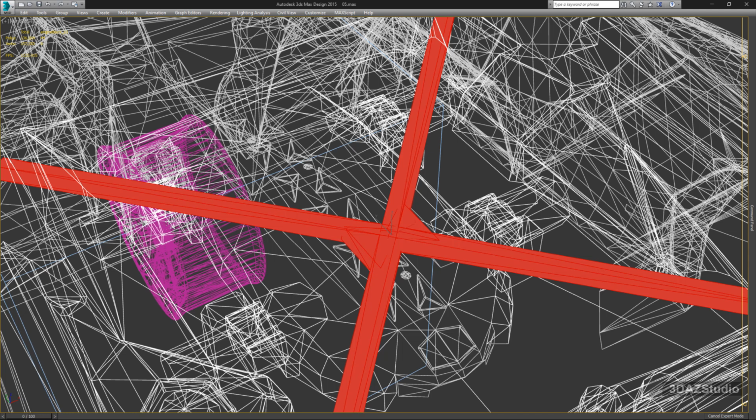While modern graphics cards can render this topology, it's best practice to adhere to clean mesh principles, allowing for overlapping vertices and edges but avoiding intersecting faces. Rather than attempting to fix the existing topology, I've decided to completely redesign this component. It's a relatively simple part, so a full redesign will be quicker and more effective.